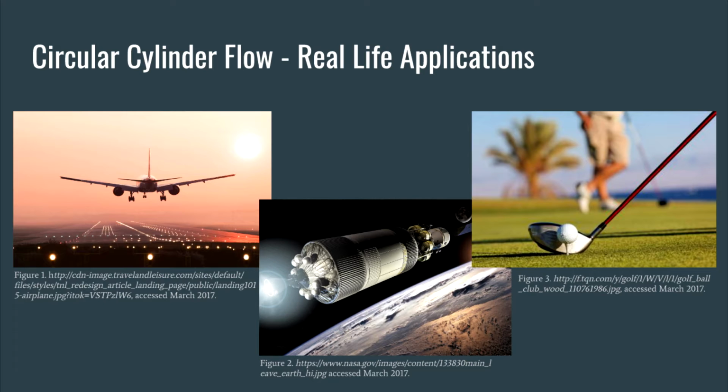In most cases, engineers study the flow around cylindrical objects in order to reduce the effects due to drag. Increases in surface roughness will increase the thickness of the boundary layer and move the separation point closer to the stagnation point. The separation point is controlled in man-made objects such as the landing gear and golf clubs by minimizing the cross-sectional area, which minimizes the effects of flow separation. The materials used are also smooth, minimizing the effect of the surface roughness on the separation point.